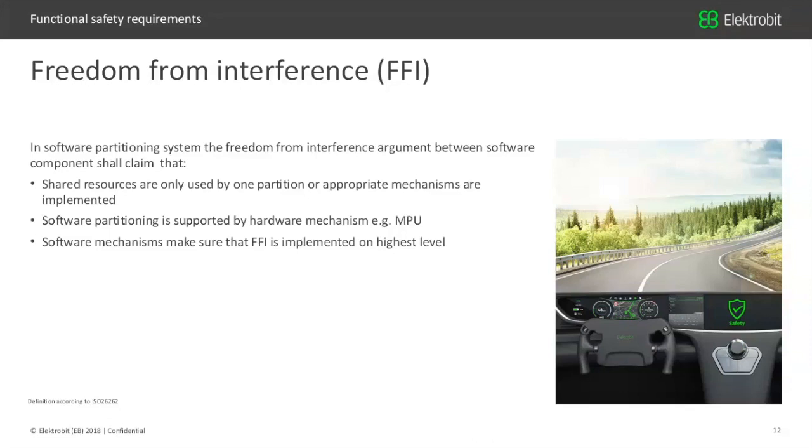To assure that I can separate it, shared resources are only accessible for a partition for a certain function. I need to separate functions from each other. I need to separate monitors from the functions which they monitor. And I have an easier life if I apply the freedom from interference concept on the highest level possible.